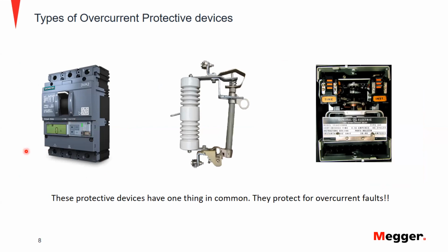It uses a bimetal element that is heated with a load current. So when an overload or a short circuit occurs, the bimetal inside the molded case breaker flexes and kicks the breaker off a latch. And then it actually breaks the circuit inside the molded case breaker device and the housing.